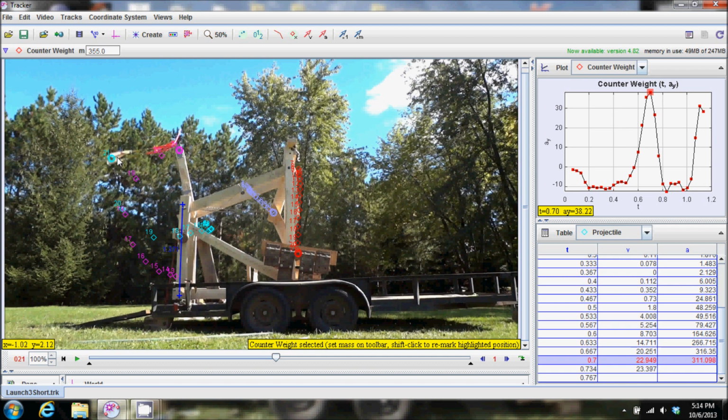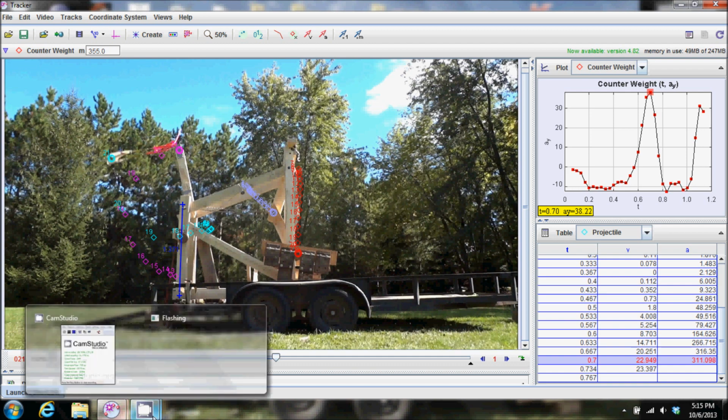the projectile is 90 degrees to the arm, and I know the acceleration there, and the mass of the projectile, and the length of the arm, the length of the cam. I can figure out the tension in the chain. I got about 13.3 kilonewtons, or 3,000 pounds. It also tells me the acceleration of my counterweight here, and through the geometry of the linkage, I got a number within 1%. So we could assume that the video analysis is going to be accurate to our real-world scenario.